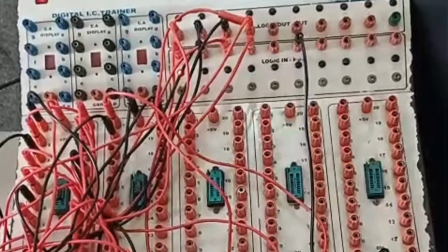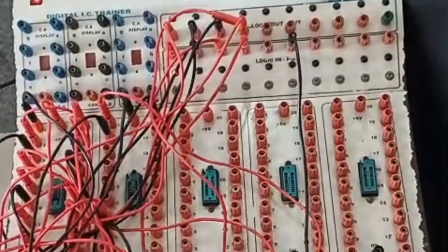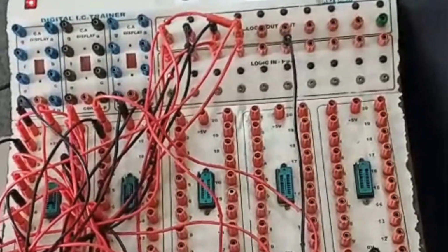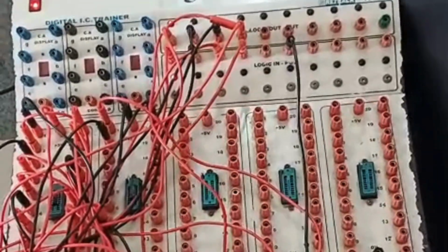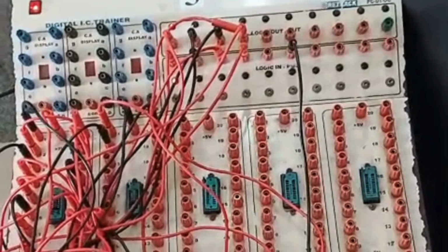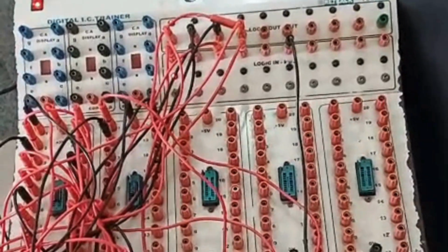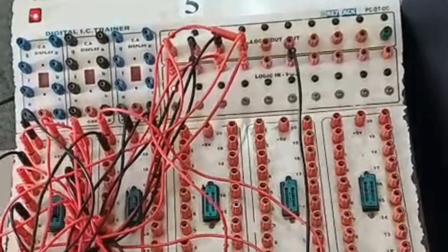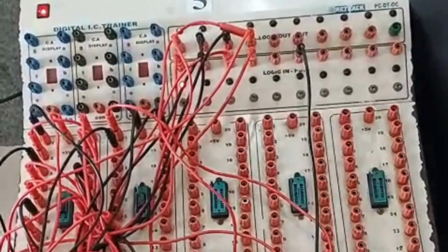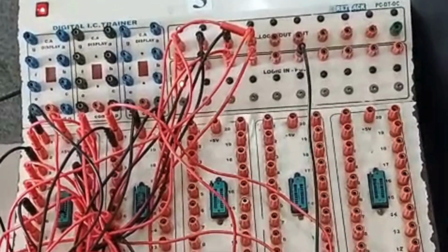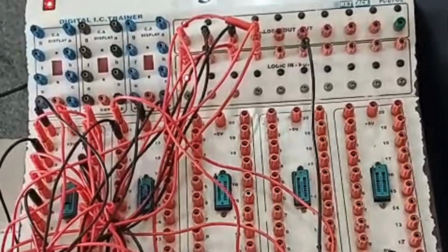Let us give the ninth clock pulse. Here the states are repeated, because the first state was 1000 and the last state is 0000. So at the ninth clock pulse, the states are repeated. We can say that a 4-bit Johnson counter gives us 8 different states, and at the ninth clock pulse the same states are repeated. Here we loaded initially the data 1000, and from that data we can get 8 different states. So this is the realization of a 4-bit Johnson counter.